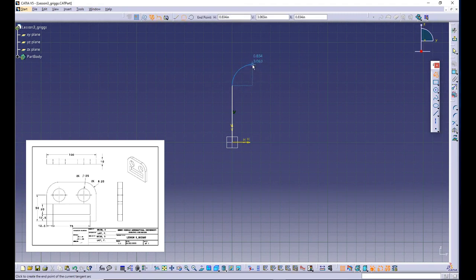But I also want to lock in a 90-degree right edge there. And then I'm going to continue on with my line going forward, locking in that tangent relationship if I can. Click, drag away, and release to form that 3-point arc, locking in my 90-degree angle, making sure that it's horizontal with my original line on that other side.